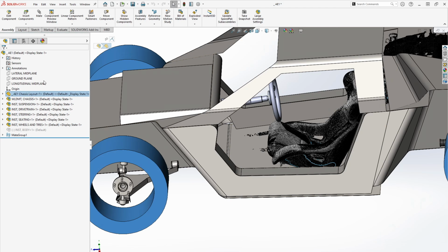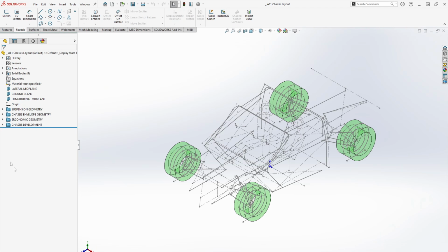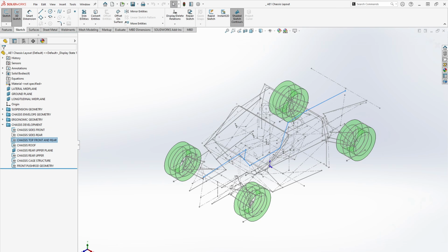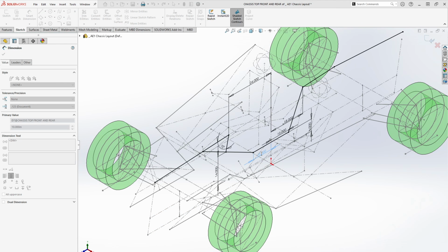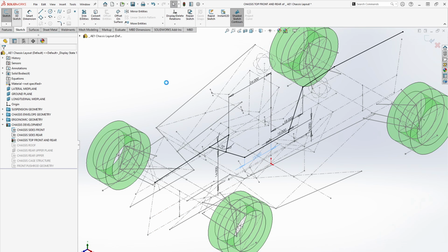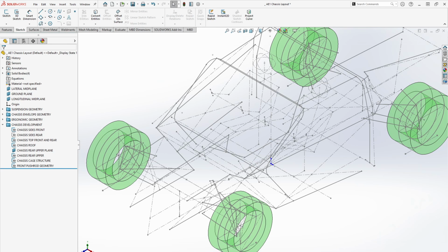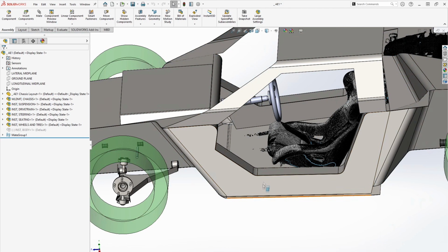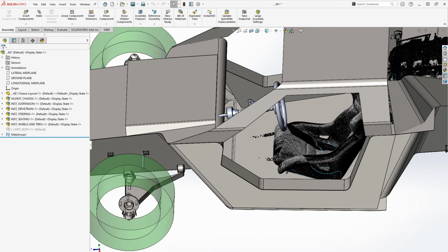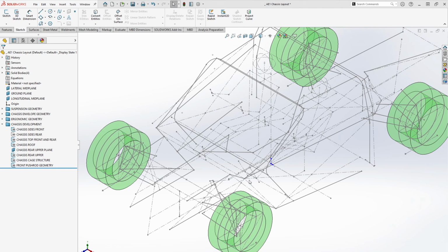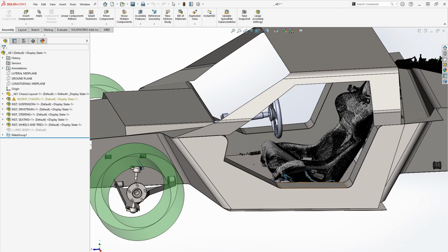So if I go over to my root file and I open up the 3D sketch that controls that ergonomic entrance area, it's at 20 inches. Let's say I drop it down to 10, make it 15 instead. Okay, I'll exit that 3D sketch and then I jump back to my main assembly, and the part's updated, and this incline is now much closer to the seat than it was. And I can do it 5 more inches and you'll see that it's moved back even further. It's almost in the seat now.